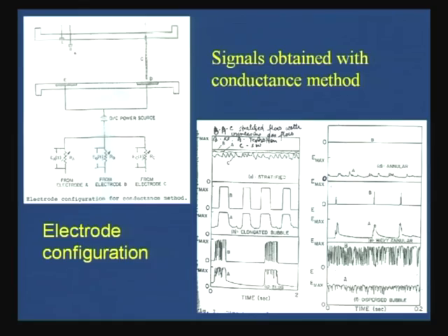It is very difficult, okay, because slugs follow very rapidly, then there is an aerated liquid slug, again Taylor bubbles, it is not very easy. But if you observe this particular probe signal, you find bubbly flow and slug flow are definitely completely different. In bubbly flow we just have a totally fluctuating signal, and in slug flow, if you observe this slide which I have shown here,